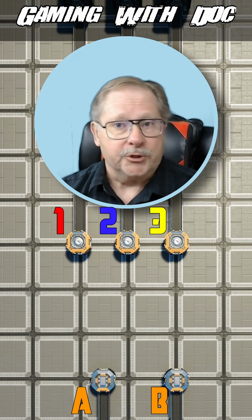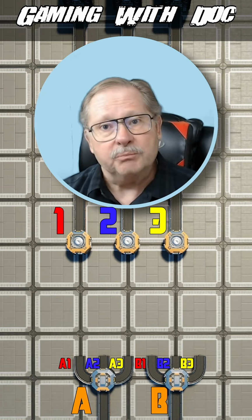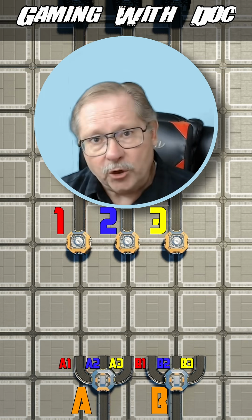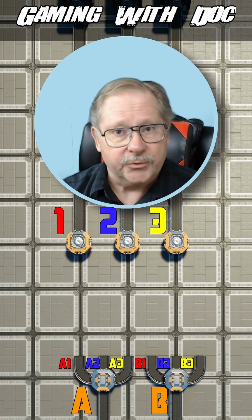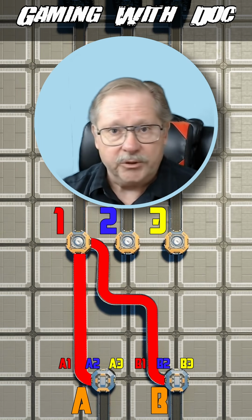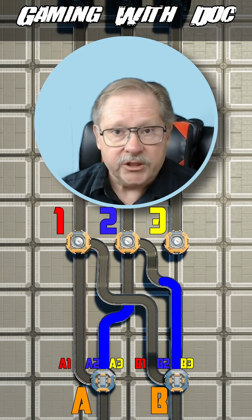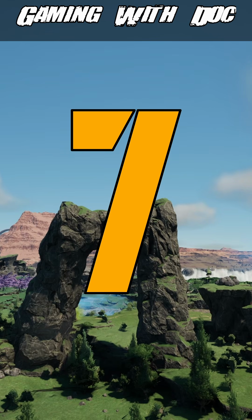Let's reverse the mergers and splitters. Split each input conveyor into belts equal to the number of outputs. This ensures that no belt is overloaded. In our case, we split each input into 3 outputs. Then we merge 1 belt from each input belt, so we merge A1 with B1. That becomes one of the outputs. Do that for each of the outputs, and you have a perfectly balanced conveyor.